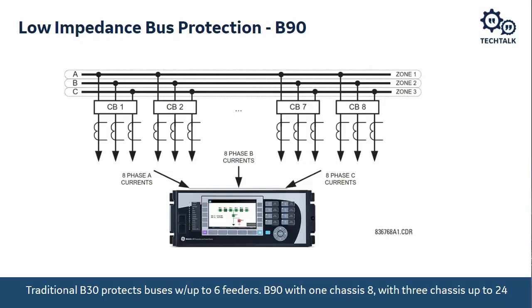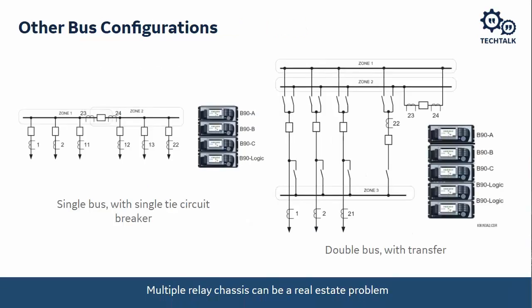There's a few issues though, right? Most of our industrial switchgear lineups look like this bus to the left here, where we have breakers connected to a bus, and we typically have a tie. Now, 2 of those breakers on each side of the bus are going to be mains typically, but nonetheless, it looks like that.